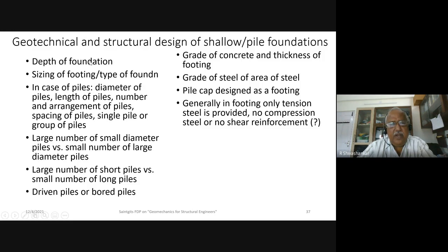So if a design problem is given to a group, let's say a group of 10, 15 people, each will come up with a different design, because there are so many options. You can have a large number of small diameter piles for a structure, or a small number of large diameter piles, or you can have a large number of short piles or a small number of long piles. Again, you can have driven piles or bored piles.